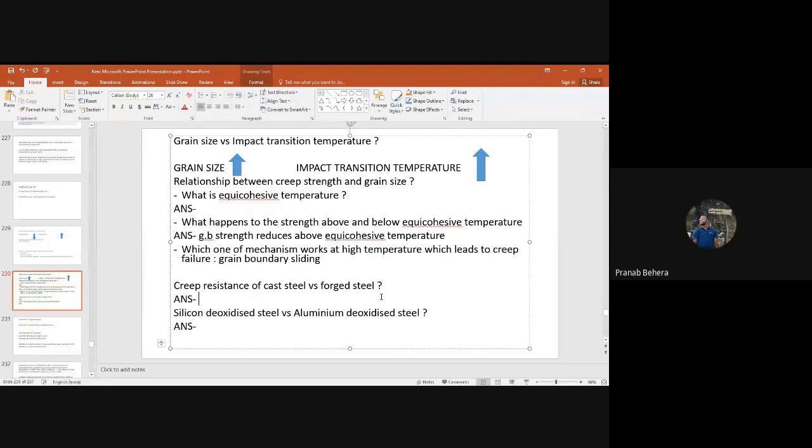But if you keep it for a longer interval of time at high temperature, then grain growth may happen at the end. So what will happen now? If you do not keep it at a very high temperature or for a long interval of time, what will the grain size be? Finer strain-free grain. Finer grain. Why finer grain? Because of recovery and recrystallization, right? Is it okay?